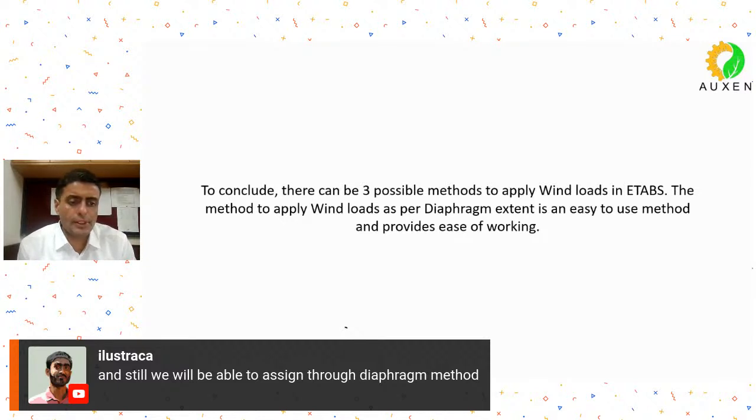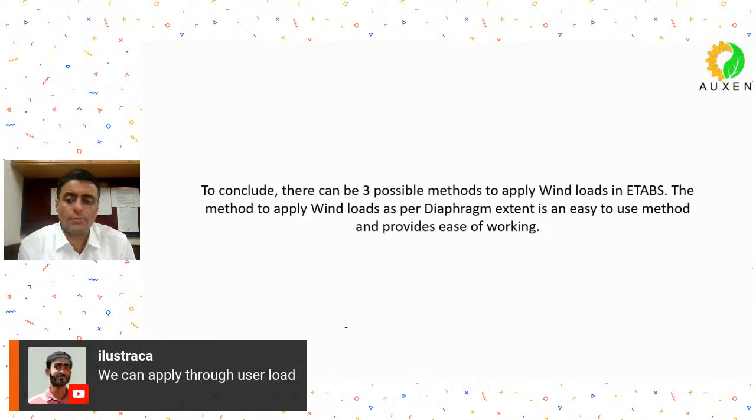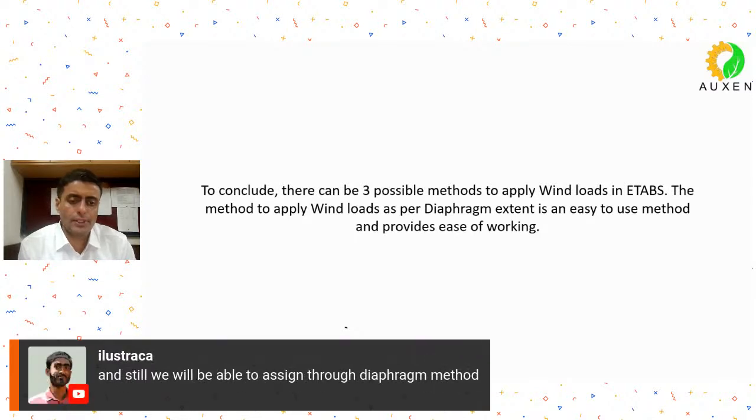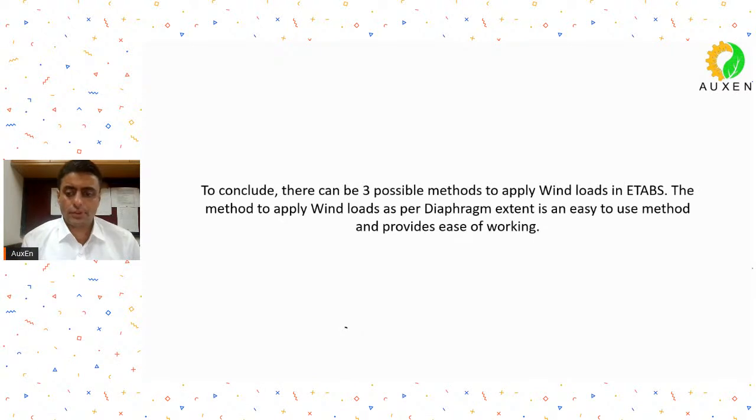Yes, Mr. Sandeep is saying that if we have problems with any of the coefficients, we can apply it through the user load option. Right. We have the option of assigning it through user load, and we can assign it to the diaphragms directly. Right. Correct. So I hope this discussion was helpful, and you understood the various possible methods to apply wind loads, and which method will be of more advantage to you.